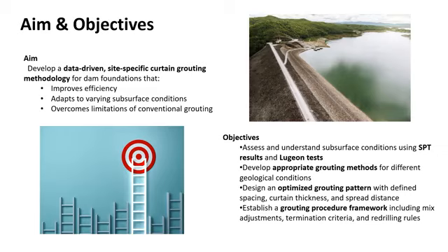First, to thoroughly assess and understand the subsurface conditions using the standard penetration test results and Lugeon permeability tests. Second, to develop grouting methods tailored to different geological conditions. Third, to design an optimized grouting pattern that specifies the spacing between grout holes, curtain thickness, and how far grout should spread to effectively seal fractures.